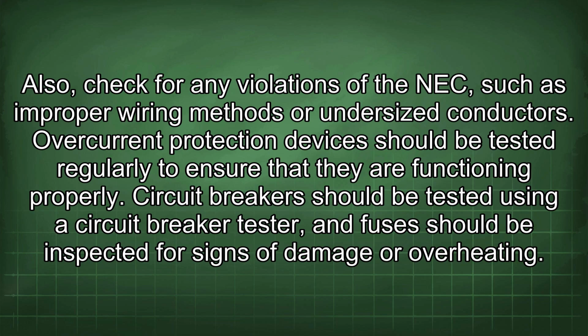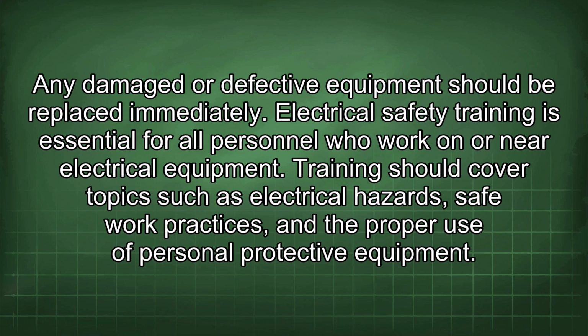Overcurrent protection devices should be tested regularly to ensure that they are functioning properly. Circuit breakers should be tested using a circuit breaker tester, and fuses should be inspected for signs of damage or overheating. Any damaged or defective equipment should be replaced immediately.